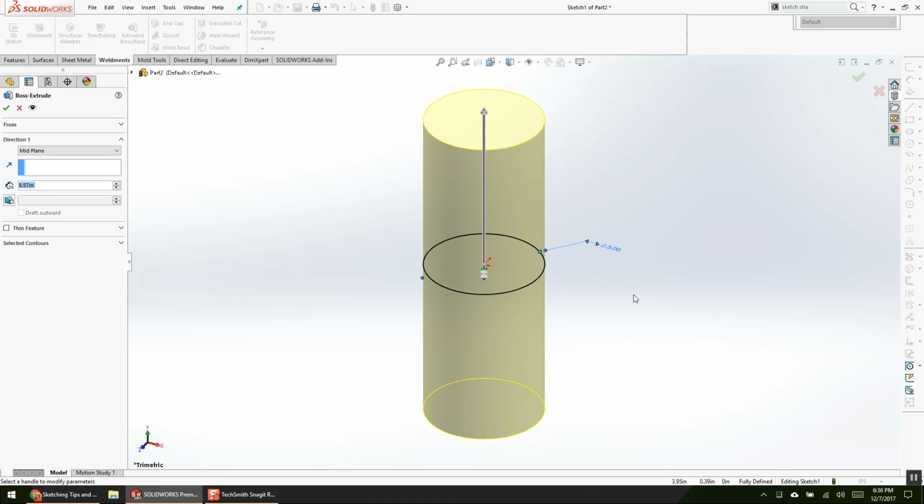Why do we do mid-plane? Because the origin is always in the middle. A plane at the very top where I have a face does me 0 good. A plane in the middle of my part, because my face is my face, right? I can still mate to my face. I can still do everything on my face. So a plane and a face occupying the exact same 2D space provides me 0 benefit. So even if the plane in the middle I never use, I at least have an opportunity for benefit, right?